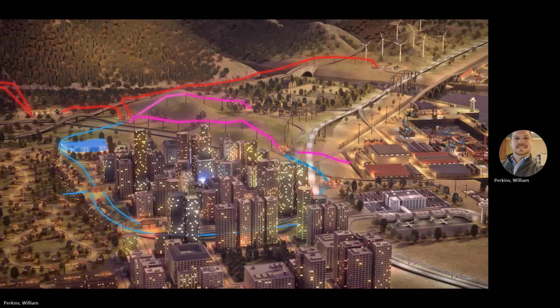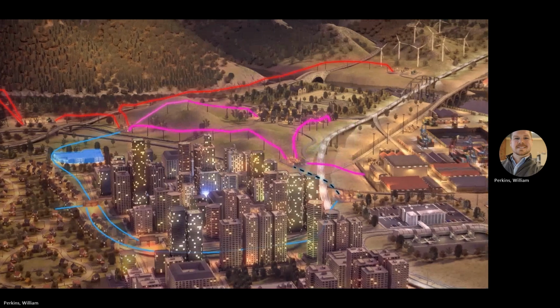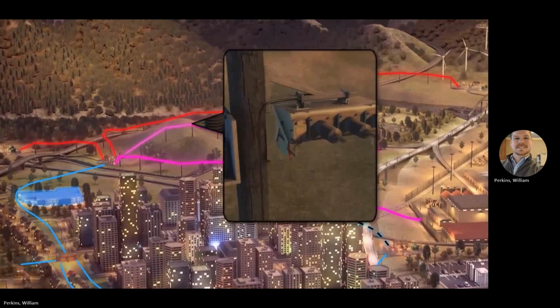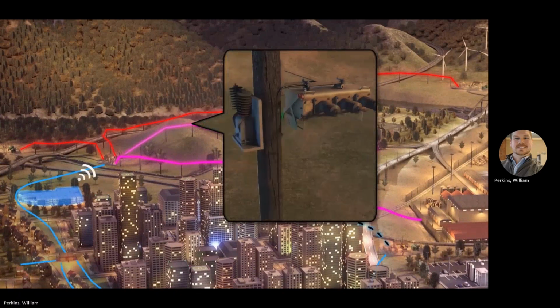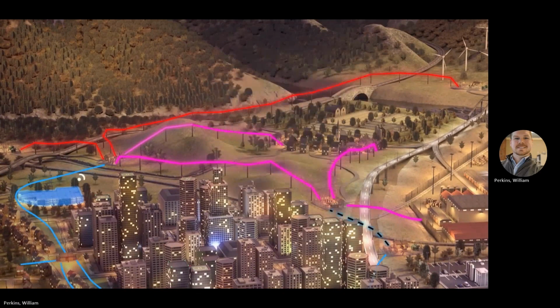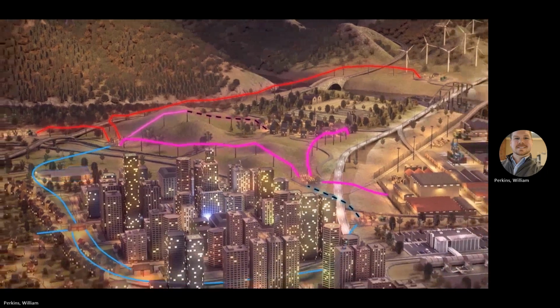The backfeed from substation 3 is no longer required, and so the SCADA operator can open its outgoing switch. With the load removed from the lower side of the network, the rural community outgoing switch from substation 2 is closed, creating a parallel circuit for the area. The final step for the SCADA operator is to reopen the GX switch to disable the backfeed to the rural community, restoring the standard operation of the whole network.